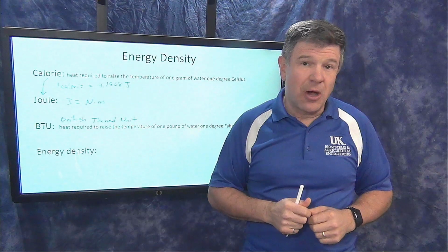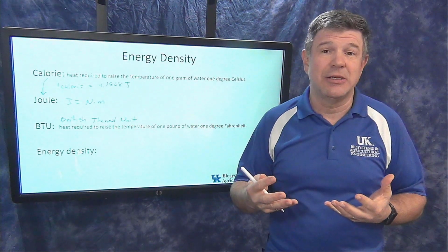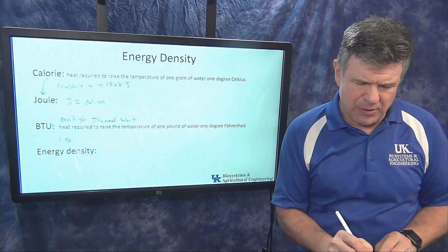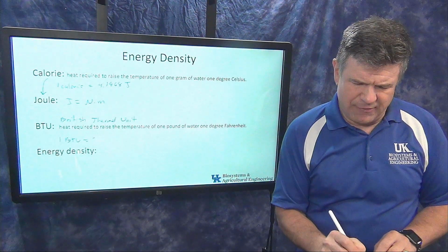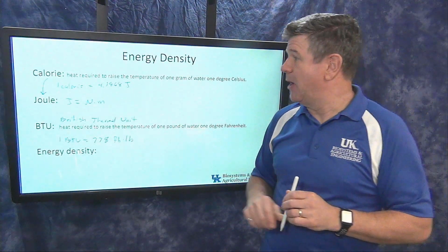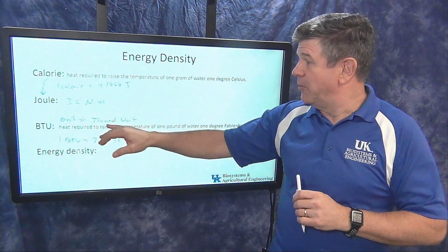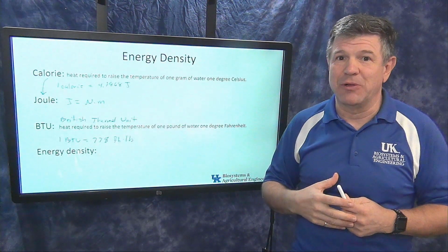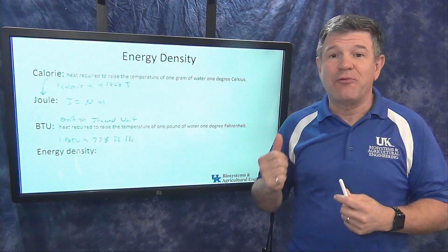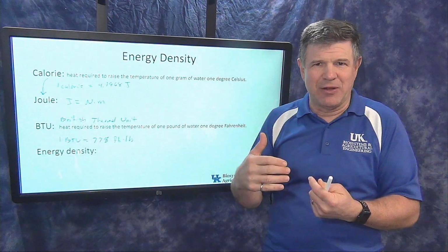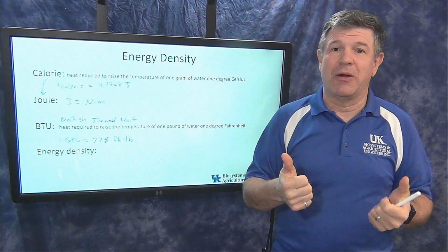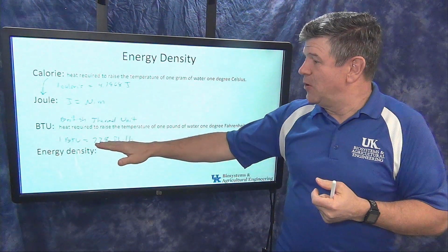So now we're going to need to know a conversion. When we start doing some calculations with this, we need to understand a conversion. So the key conversion is that 1 BTU is equal to 778 foot-pounds. So there we go. We've got Newton meters up here, which factor into our power equation really easily if I can put the time into it. Down here I've got 778 foot-pounds. I can take foot-pounds if I know foot-pounds per second. I have that conversion, 550 or something like that, to get me to horsepower, so I can do that. So these are the units that we're going to be working with.